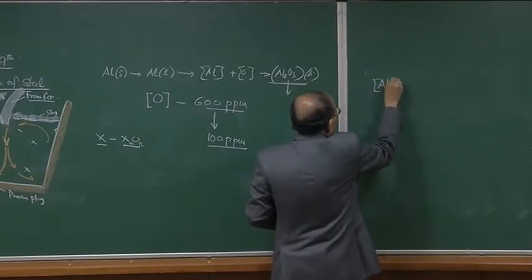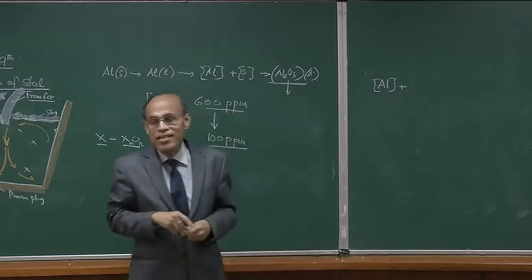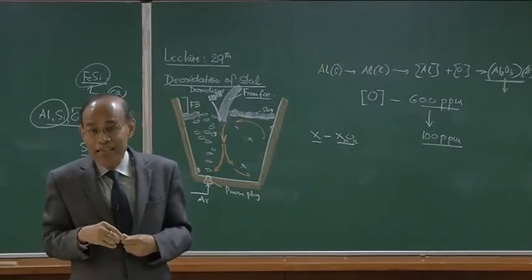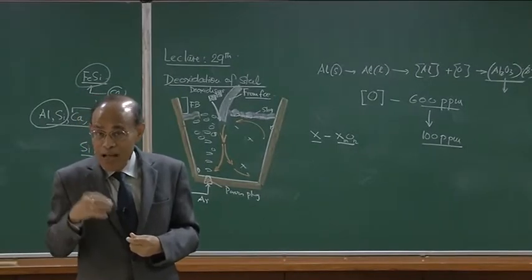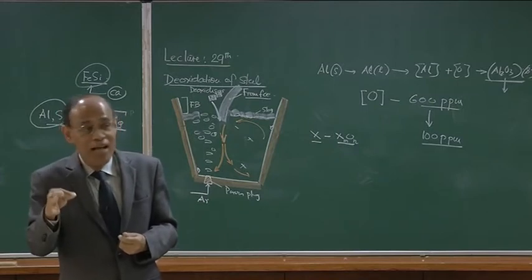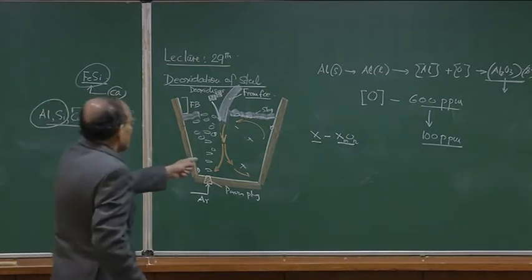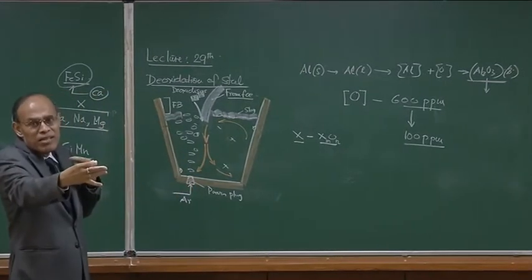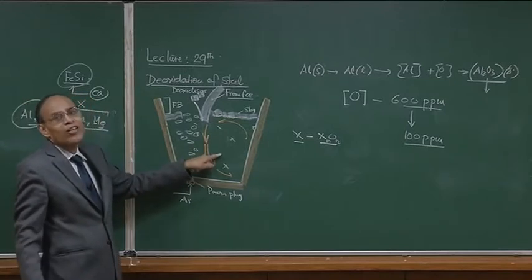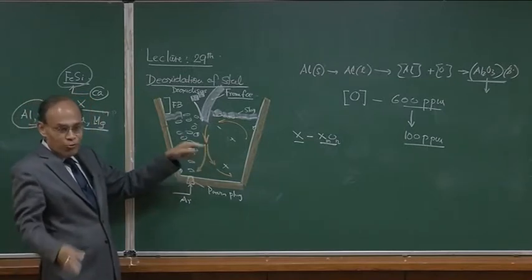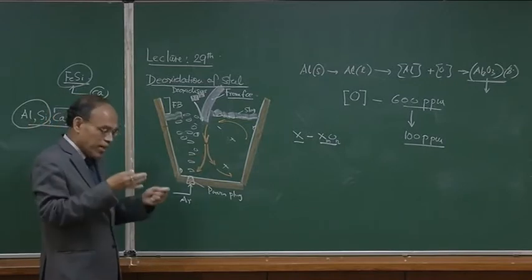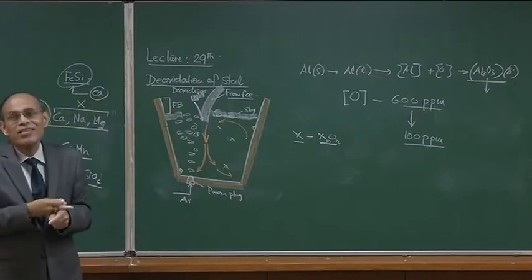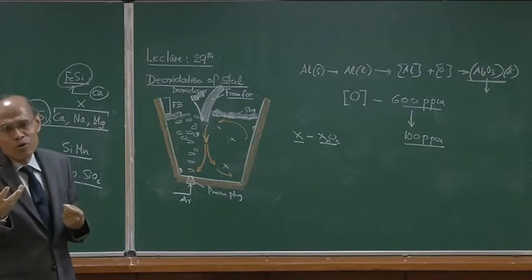Al dissolved by L. So the first part we understand is the melting and dissolution, which is a heat and mass transfer phenomenon. Melting is a heat transfer phenomenon, dissolution in steel is a mass transfer phenomenon, and these are going to be aided by convection. So they are going to be pretty rapid in this particular system because of the large difference in temperature, and because the steel does not already contain a large amount of silicon, etc. So the driving force for mass transfer, the gradient of concentration and gradient of temperature, are enormous, and because you have a good amount of stirring, and these are low melting point constituents relative to steel.